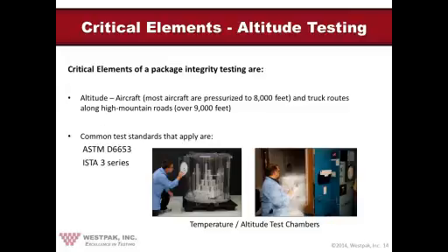There were a number of questions that occurred about the whole area of altitude testing. We say that most aircraft are pressurized to 8,000 feet, and that's true. In fact, almost all of them. And the reason is they're all piloted by pilots, and the pilots demand 8,000 feet because they go up and down in these aircraft, and that pressurization differential will cause nitrogen asphyxiation in the blood, what we call the bends, if they're overexposed. So that was one of the reasons why 8,000 feet is the normal pressurization level.